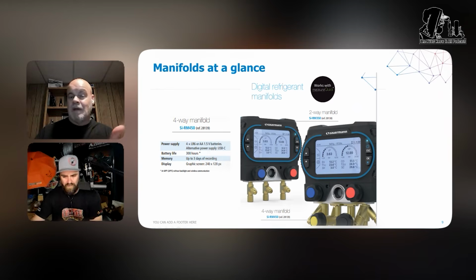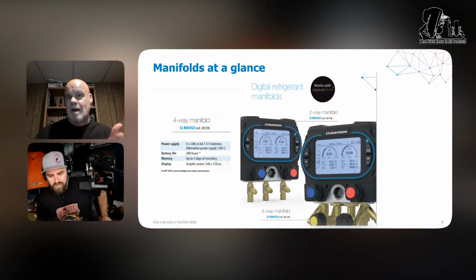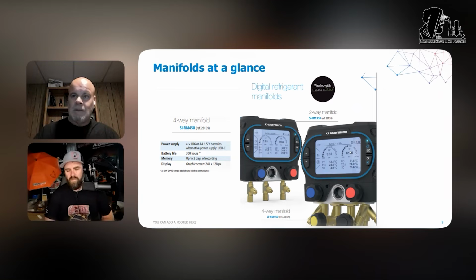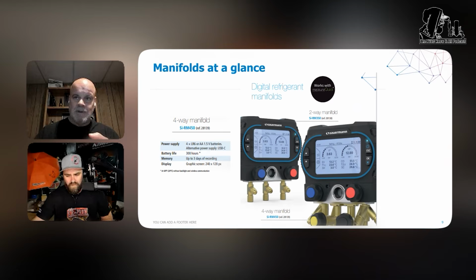But if somebody wanted to pull vacuum, which we all know is purist, that's not the traditional way to do it. But we have one if somebody wanted to do that with the latest and greatest in both technology, but also durability for internal components. Pirani sensor in the vacuum probe. We also have micron gauges built into here. It goes as low as 50, upwards of 25,000 microns.